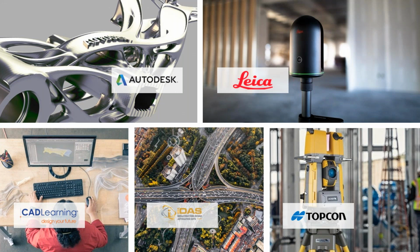So that scanner is actually used for interiors predominantly in the built environment for architects and stuff like that, but it can be applied in a wide range of applications if you know what you're doing. But if you're looking for something more rugged, so if you were on the construction, civil engineering, mining segment part of things, I would say look at the Topcon. What you're seeing on that picture is a GLS 2000. It is a really rugged scanner, very big. It looks like a total station. It's got the reminiscence of that if you have used one before. And it has a really wide or long ranging scanner starting from the entry level being 300 meters. I think it's about 120 meters, and the high range going up to 500 meters, which is a lot.